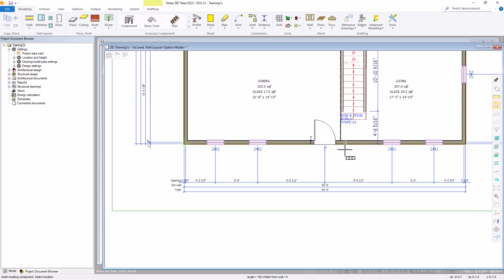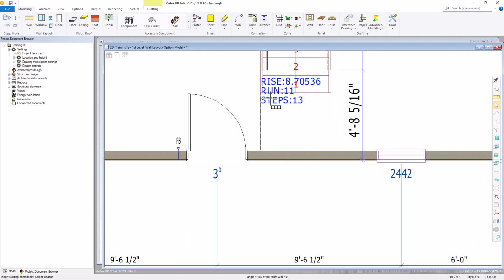Next, select the exterior wall again. To set the location, select the center line of the stairwell wall. Select the other stairwell wall to add the other double stud macro. Select the escape key or right mouse click and select Exit to close the command. Now we have two double stud macros in line with the stairwell walls.